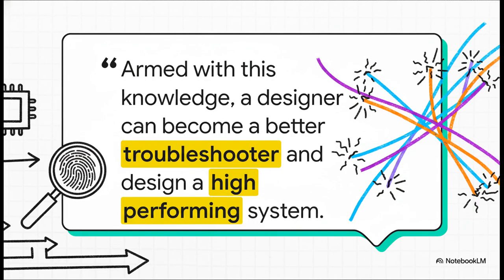You know, in the end, it all comes down to this really powerful idea. Once you understand that digital crosstalk shows up as a signal-dependent error, not just as random noise, it totally transforms how you approach design and debugging. It shifts your focus from just trying to manage some vague noise to meticulously managing your signal paths. So the next time you see those unexpected harmonics, you won't just see noise, you'll see fingerprints, and you'll know exactly where to start hunting.